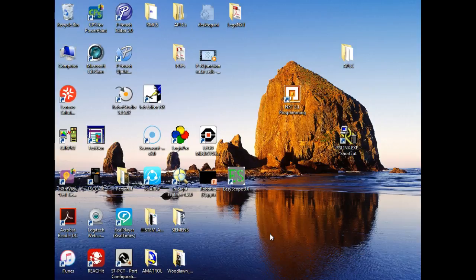Guys, you can come up here and look and see how this is wired. It's hard to tell because it's just kind of nested up here using all these jumpers. But I think the inputs are hooked up to source. The input devices themselves are hooked up to source. The outputs are hooked up. The output devices are hooked up to sink.